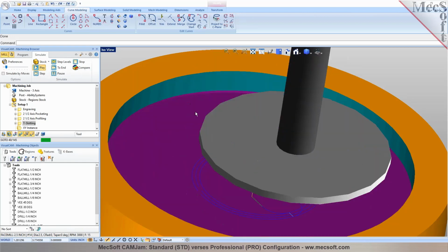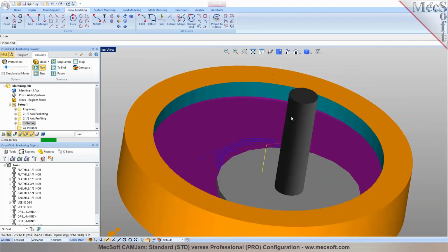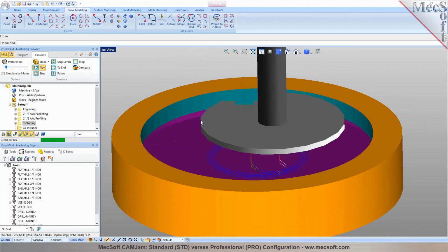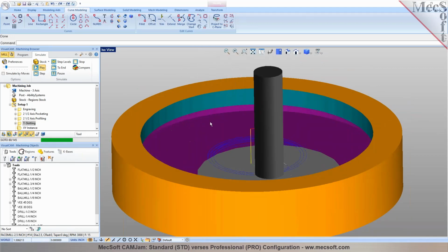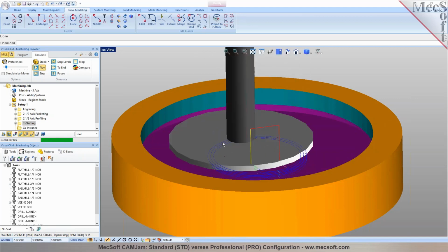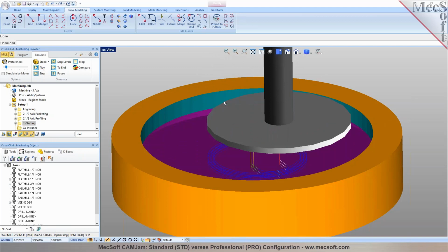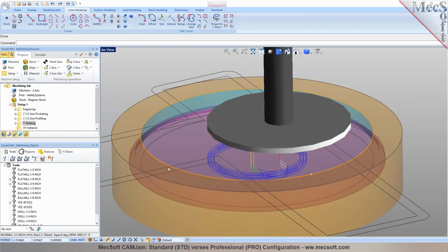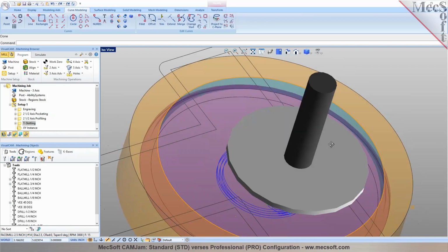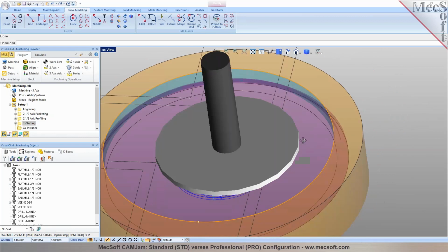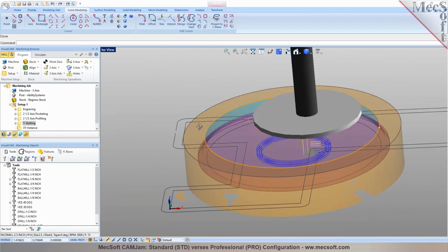Right? So when you have variable thickness, or when the thickness of the T-slot that you're trying to accomplish is larger than the cutter itself, all you got to do is pick the edge. You need to have an edge that exactly matches the T-slot right at the top and before where the T-slot begins. And this is also documented in here. As you can see, it's in the help system. It's all documented for you. Okay.